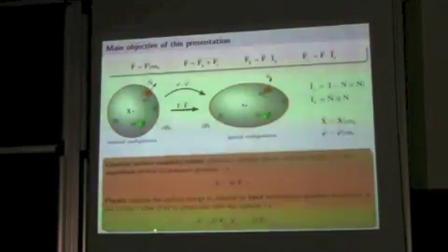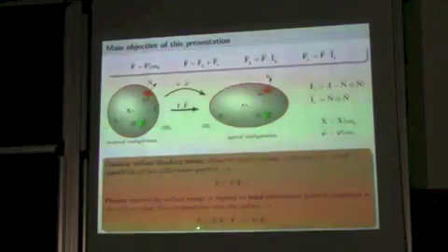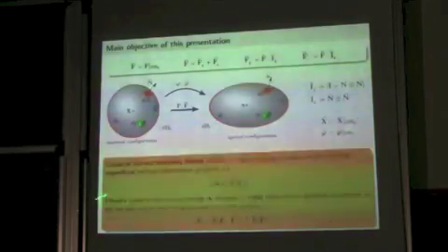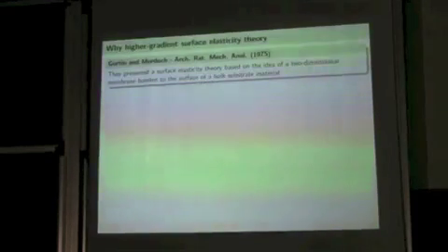onto the surface. Okay? So what we want to do here is to allow the surface energy to depend not only on the tangential part, but also on the normal part, okay? Or on the full surface deformation gradient. I will try to explain why I say physics requires this by looking back a little at the literature and the observations. So again, remember what Gurtin and Murdoch did.